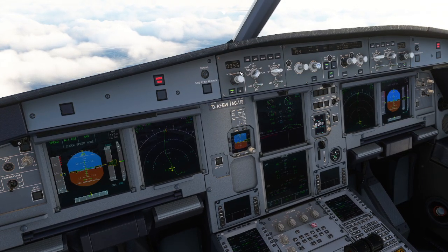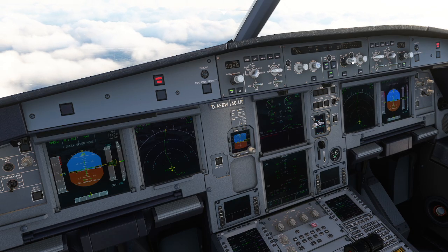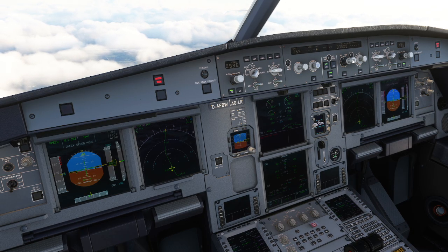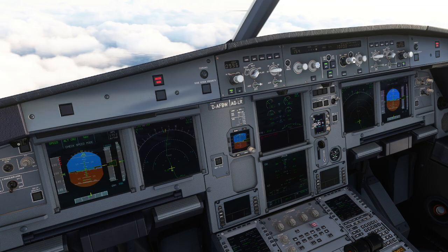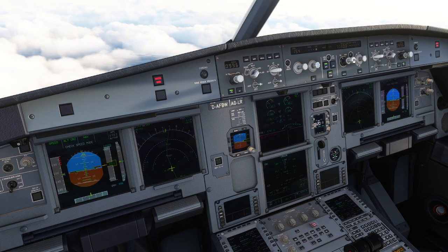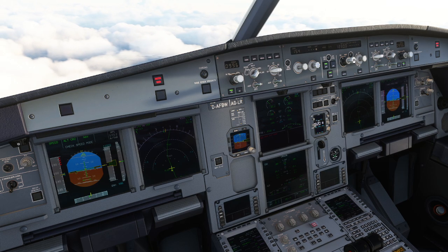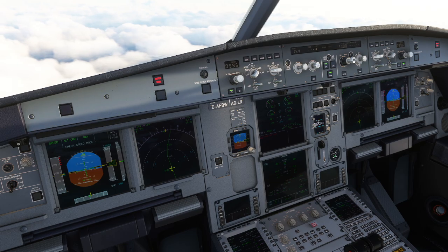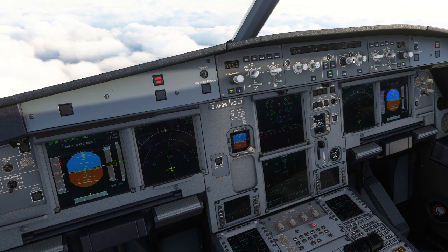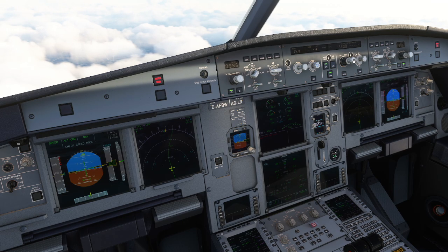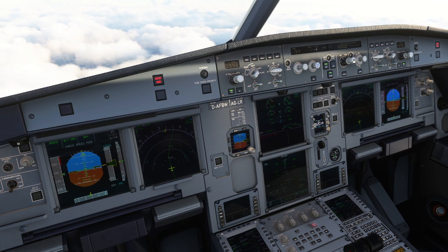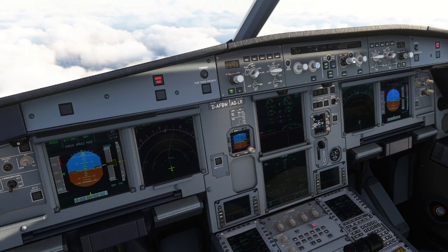Even though I have set the QNH also, still the problem is there. So during the next flight plan modification, I have done the generation, but at that time I got flight level 210, so I'm setting my altitude up to 210 after the transition altitude. So let's get it done right now. That is 210.